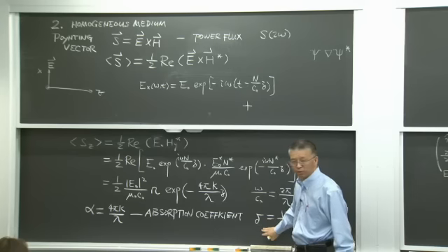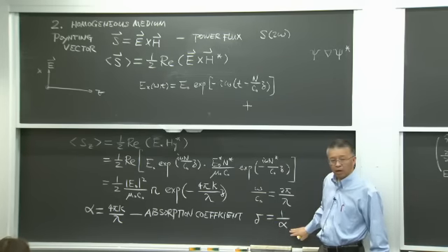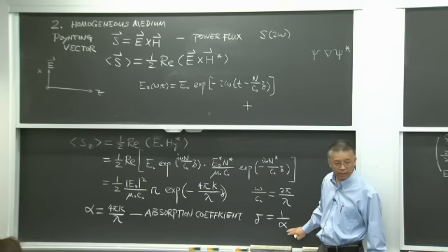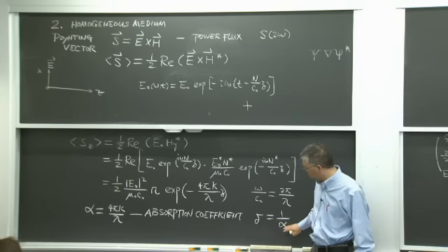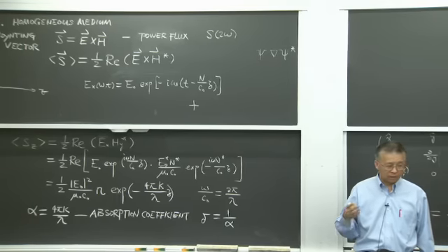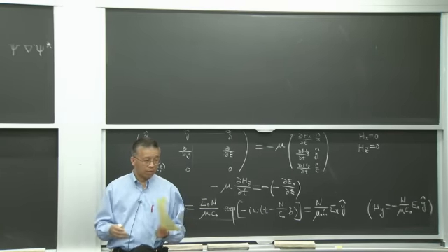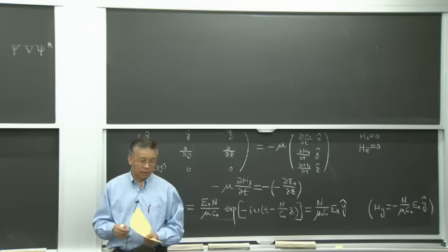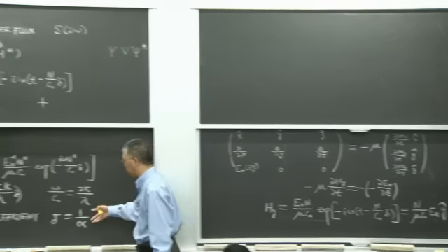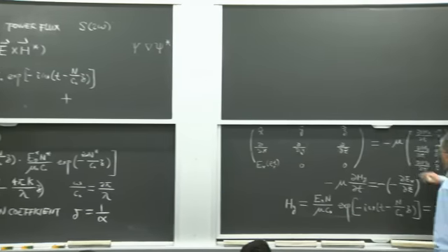This is very important when you make solar cells, because it determines how deep the photons penetrate into the material. Silicon is an indirect gap semiconductor, so alpha is small near the band gap, so it's not a good absorber. Because of that, you have to use a pretty thick material to absorb the photons, and that is a big problem with silicon photovoltaics: the material cost.